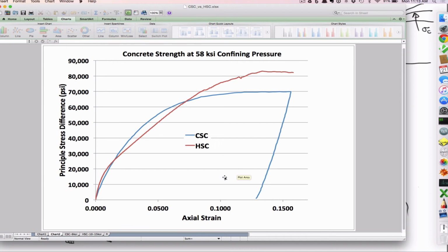And you see in this case quite a bit of inelastic flow. In fact, you can't really see any elasticity at all. The elastic range is really small. And this is not actually failure. This is just unloading. It was taken out to almost 15% strain and then unloaded. Now this is concrete. Concrete's not technically a rock, but we categorize it with geomaterials: rocks, concrete, soils. Characteristically, it behaves similar to a rock.